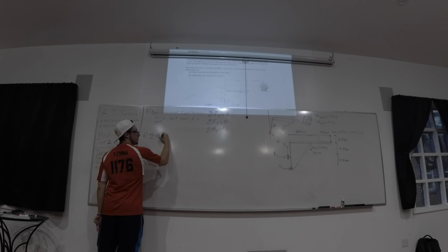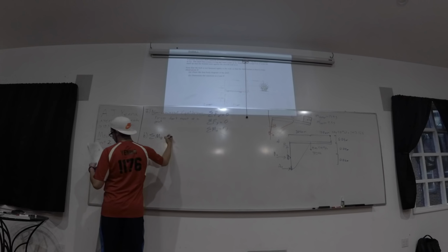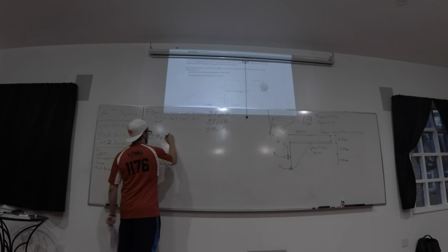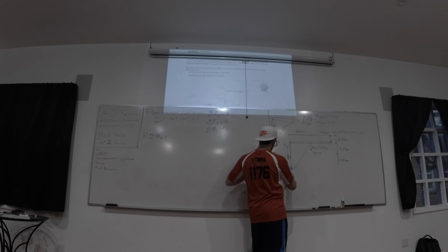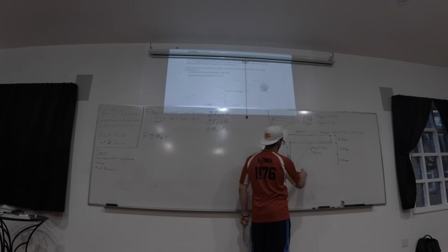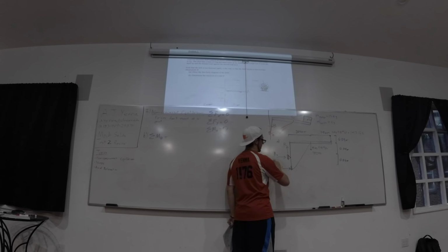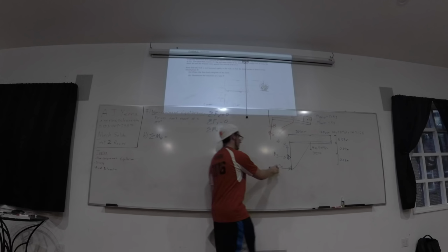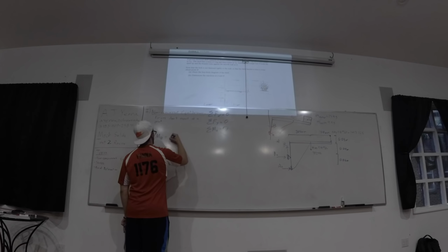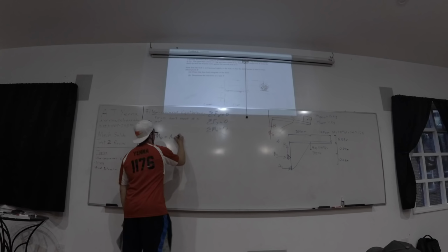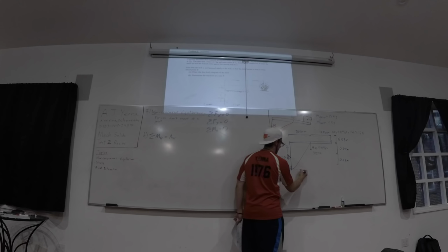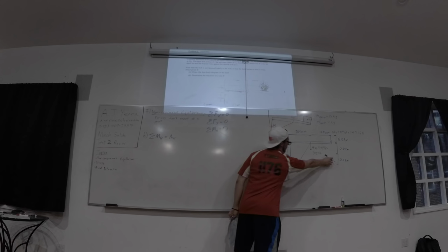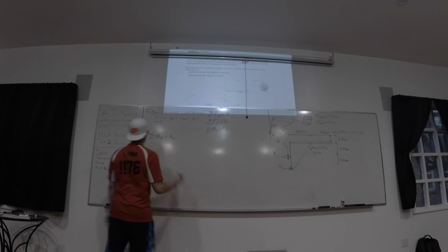summation of moment around B. So for here, we have Ax is positive because it's going counterclockwise around point B. So you get positive Ax times the distance between the line of action of Ax, which is this, and point B, which is 0.06 meters.